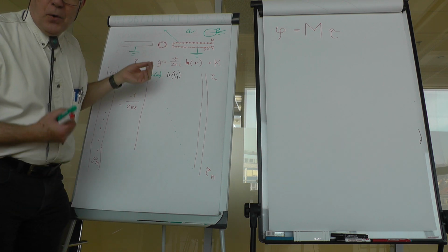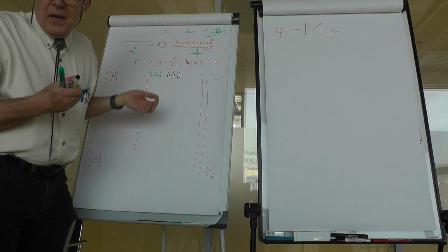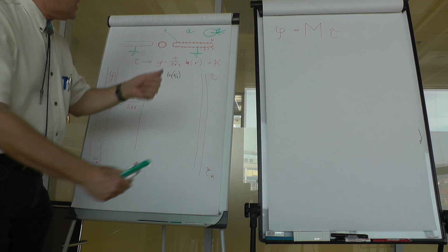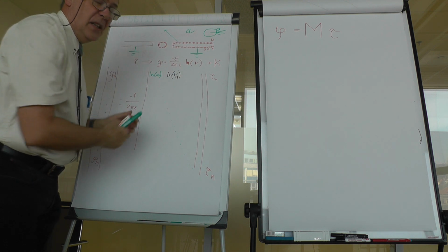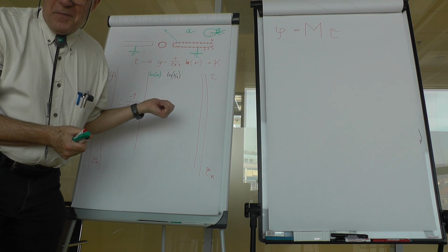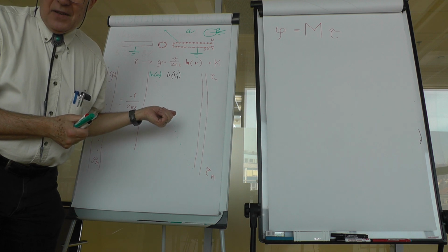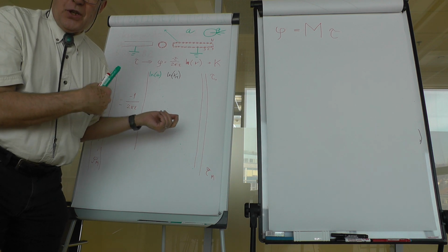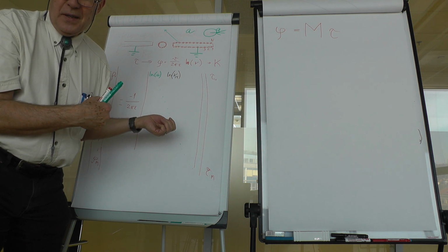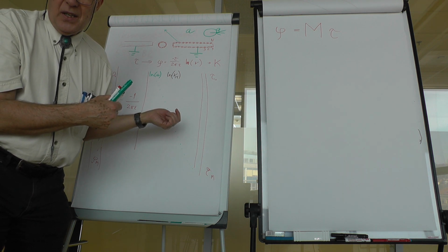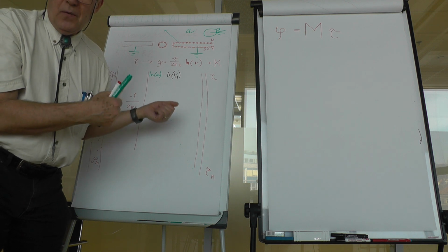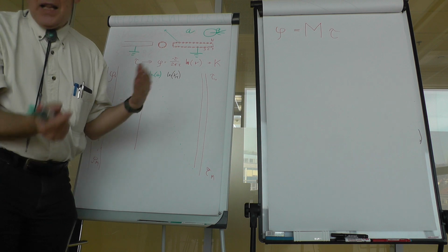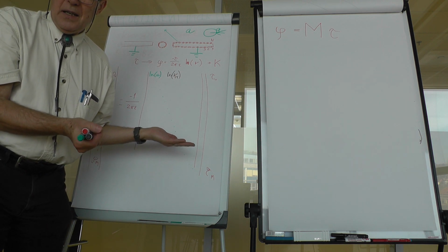So what I would do, if I measure that, well, I would take a special apparatus, connect the terminals to the structure, and it would first discharge the capacitor, then it would charge the capacitor with known charge up to a known voltage and divide voltage and charge to get capacity.